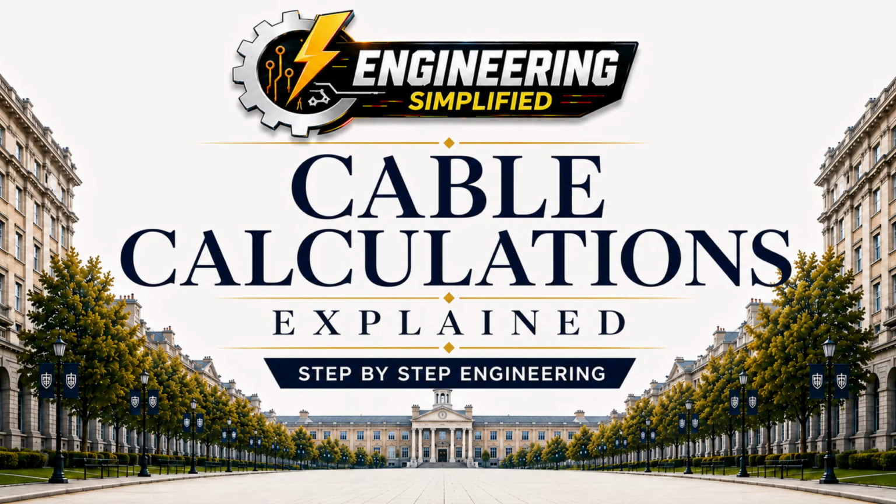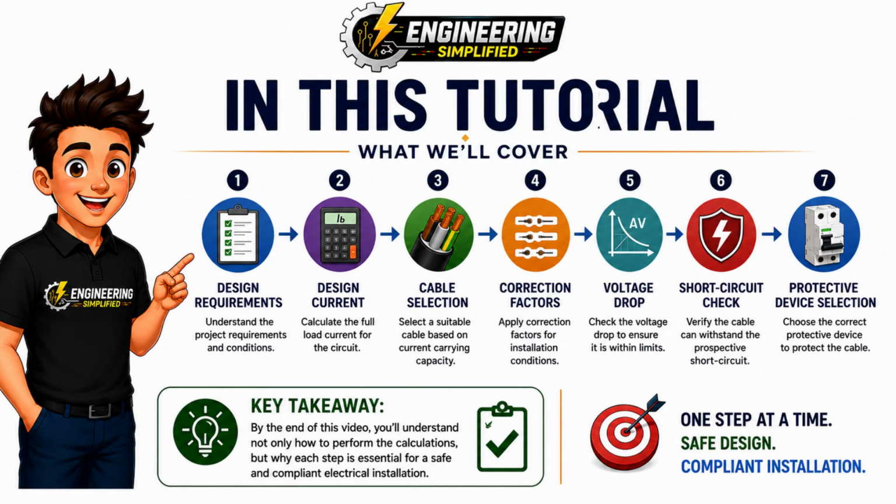In this tutorial, I'm going to show you exactly how to size an electrical cable using the same step-by-step process used by professional electrical engineers. We'll start by understanding the design requirements, calculate the design current, select a suitable cable, apply correction factors, check the voltage drop, verify the cable against short circuit conditions, and finally, choose the correct protective device. By the end of this video, you'll understand not only how to perform the calculations, but why each step is essential for a safe and compliant electrical installation.